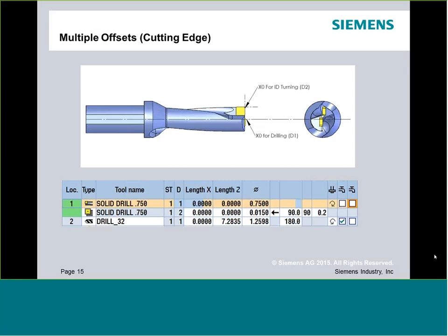First, you don't have to drill everything on center. So although the tool may have been designed to drill a 1-inch hole, there's actually an allowable range where you can offset this tool to make the hole bigger and drill it from solid. So it's not a case where I have to drill it and then come back in. And our cycle supports that. So we'll look at that here when we get to doing some drilling.